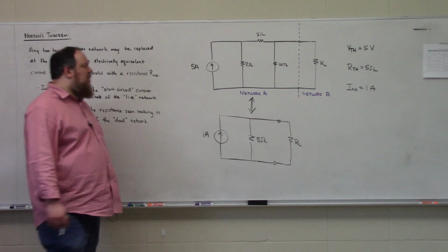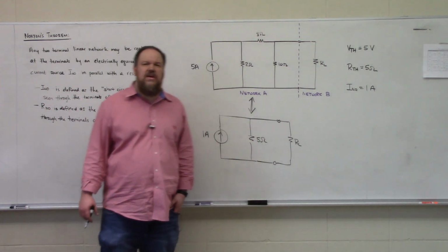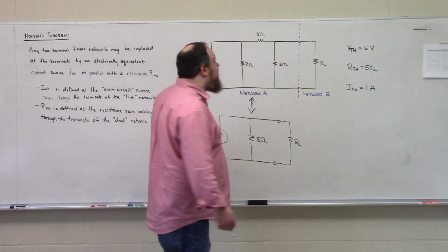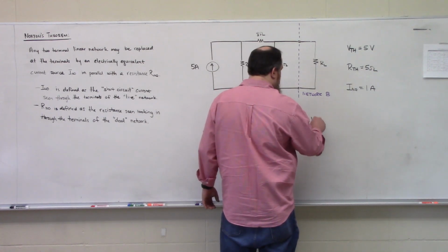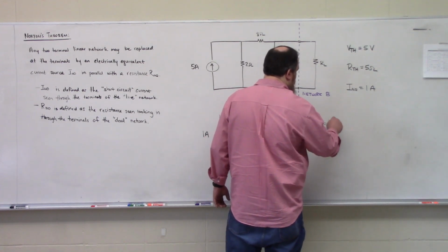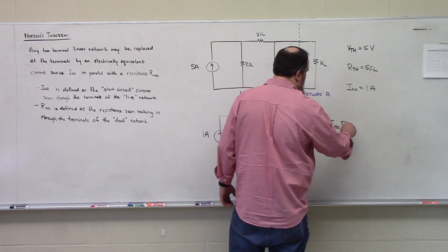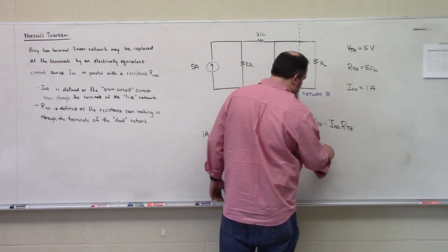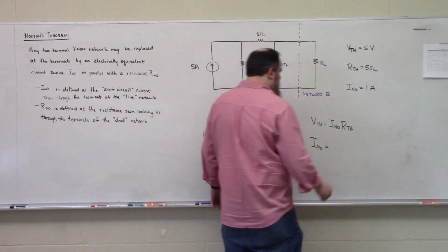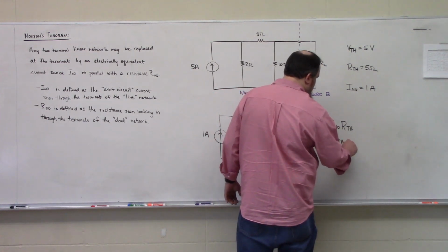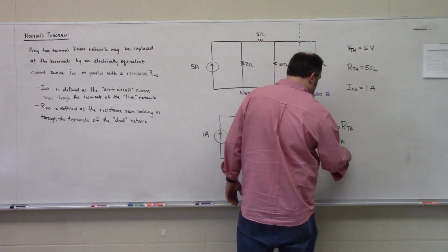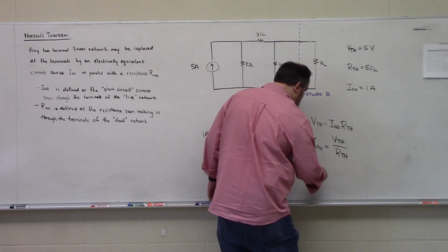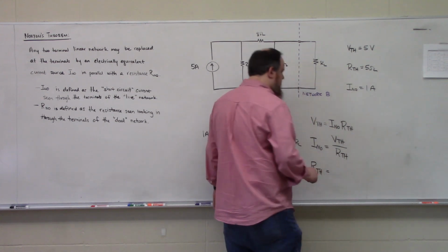And it shouldn't be hard to tell that the Thevenin equivalent circuit is simply the source transformation of the Norton equivalent circuit and vice versa, giving us the relationship V Thevenin is equal to I Norton times R Thevenin, or I Norton is equal to V Thevenin divided by R Thevenin, something that we're going to actually use when we get into Thevenin and Norton equivalents with dependent sources.